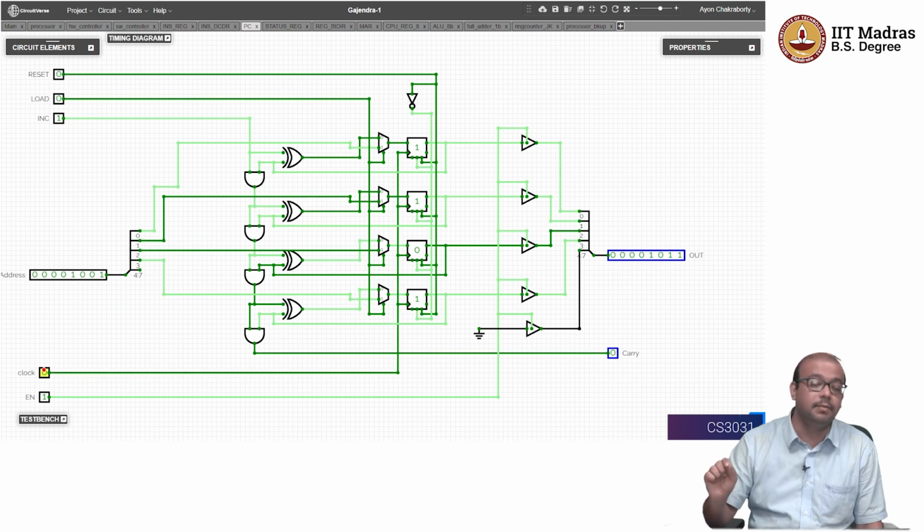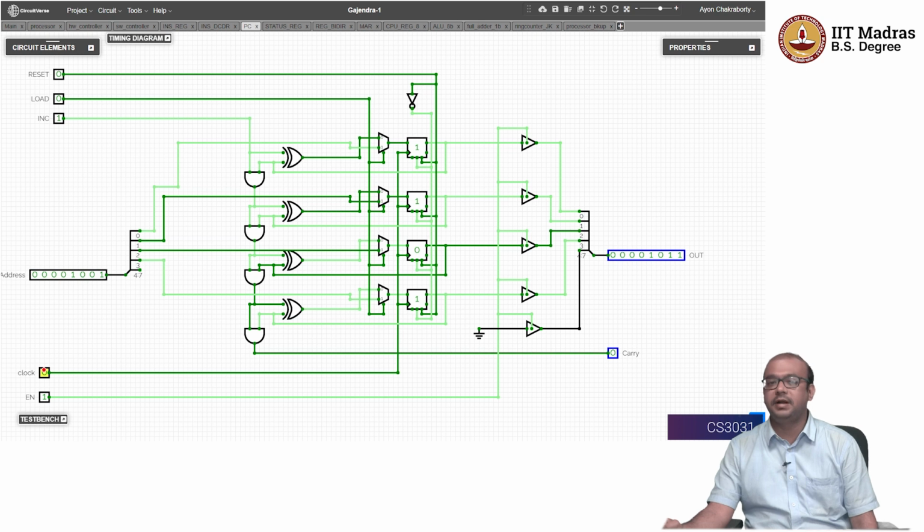So this is a very, very important feature to implement jump instructions, anything related to jump or flow of the program, right? So the program counter needs to be loaded by an external address. So the external address is basically issued from the instruction itself because the instruction contains jump. So the part of the instruction is going to tell that, hey, please go to this 9th location.